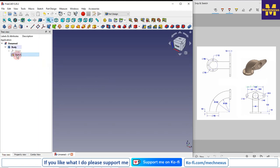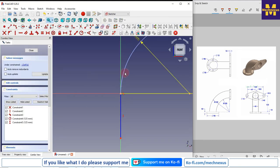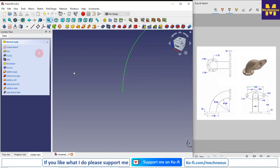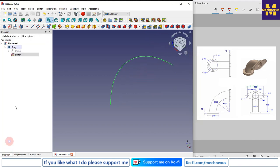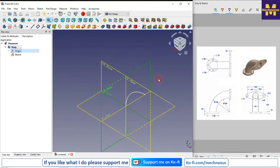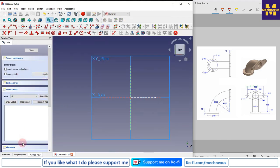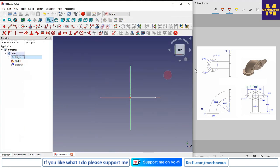So our path is in a construction, so we will remove the construction geometry so that it should be visible. So this is our path, and now I will on my plane. Now I will select the XY plane, and I will create the sketch, and I will off my origin plane, and I will switch to the isometric view, and I will draw my pipe profile.